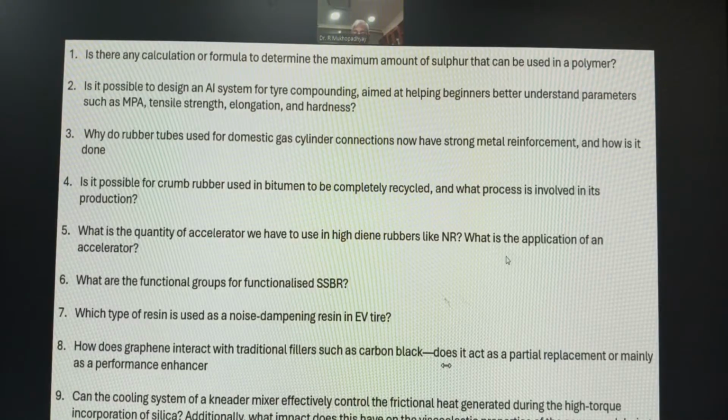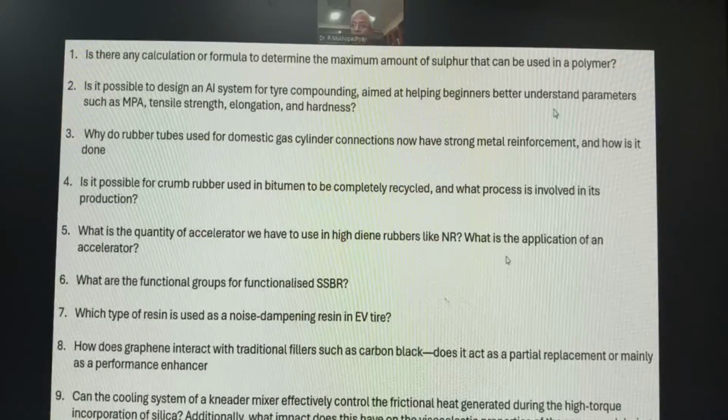Similarly here again, if you do not use an incinerator or closed chamber, it is not environmentally friendly. Only burning means fumes. Again, if you have the incinerator, the closed chamber, what they do in pyrolysis is give the tire in chips there itself in the closed chamber, and ultimately all of the rubber and mixed compound convert into oil, and you get filler carbon black, and you get steel. Even the fabrics and others, everything is decomposed.